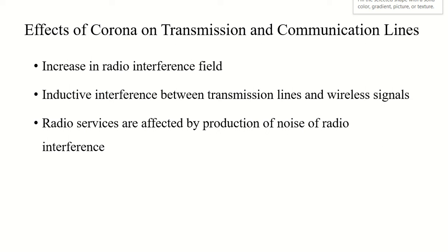And all this discussion leads us towards the fact that because of corona, the complications in my transmission lines and even the effect of my corona on other things will be very much at higher voltages. So in extra high voltage or EHV lines, the radio noise will be a very important consideration whenever we design a line, because the noise which gets produced because of this radio interference will be associated with corona, and it is mainly dependent on the voltage gradient at my conductor.